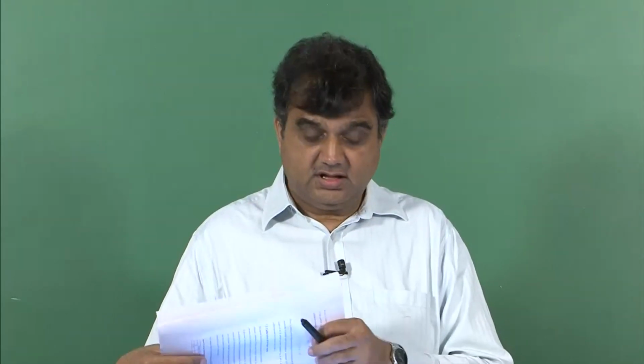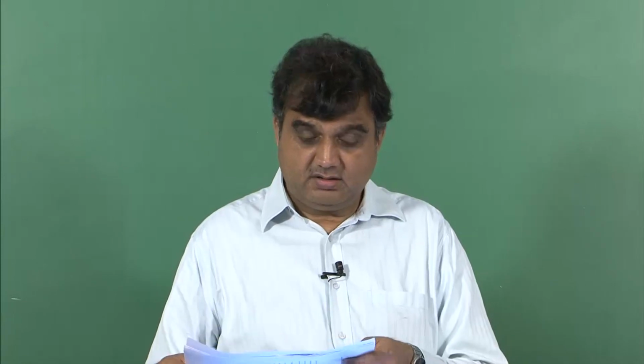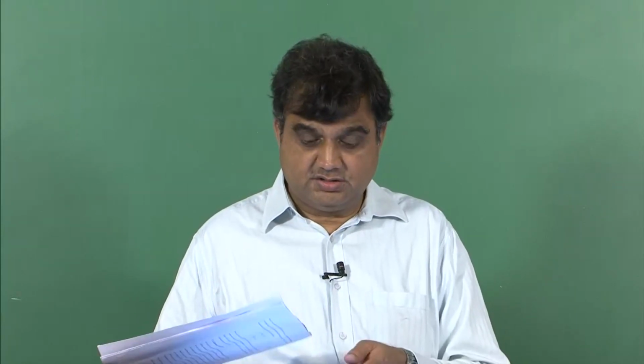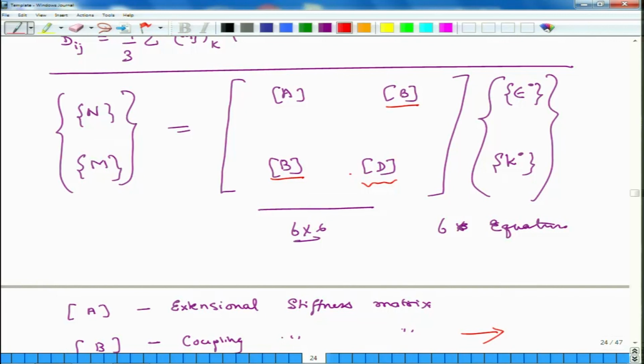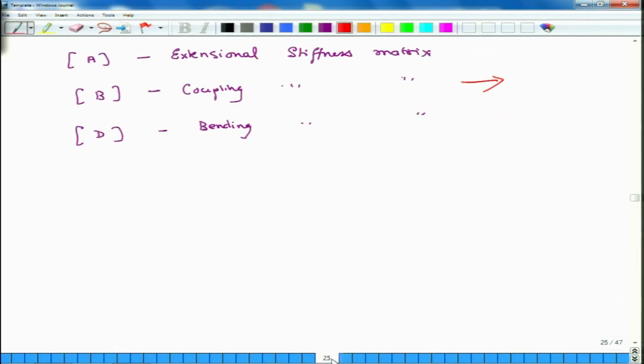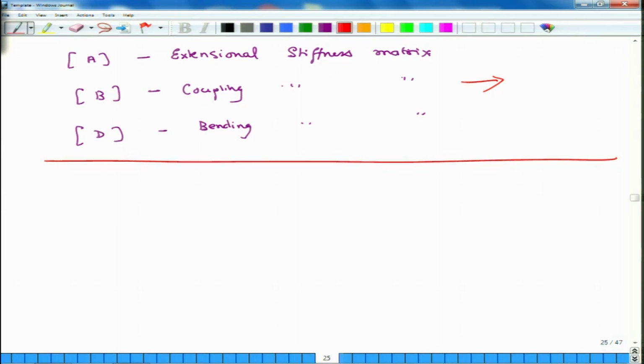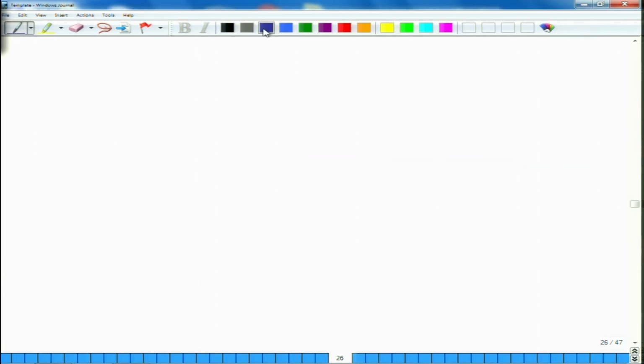And similarly, if I try to bend a plate and if the B matrix is not 0, it will not only bend, but it will also get stretched. So, that is why it is called a coupling matrix. So, this is the understanding behind their nomenclature. The next thing we will discuss in the next few minutes is how we provide names to different lamination sequences. So, nomenclature.